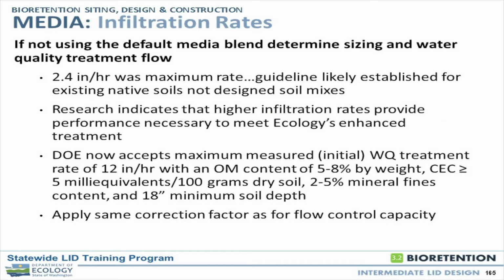There's other criteria though. There's the infiltration rates, but there also is organic matter content. It should be within the range of 5 to 8% by weight. CEC, but you know what that is? That's right, cation exchange capacity, 5 milliequivalents per 100 grams dry soil, and 2 to 5% mineral fines. So those are the guidelines for developing your own media.